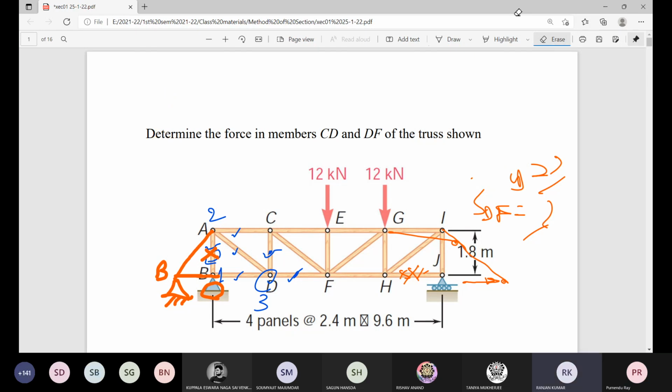Sir, because when a real structure you are considering, not this thing, this is the starting point. But when we go for designing any real structure, there you need to consider the possibility of change in length of all these members. That is, when it is under tension, there will be a tendency of increase in length, and naturally for compressive load there will be some shortening.